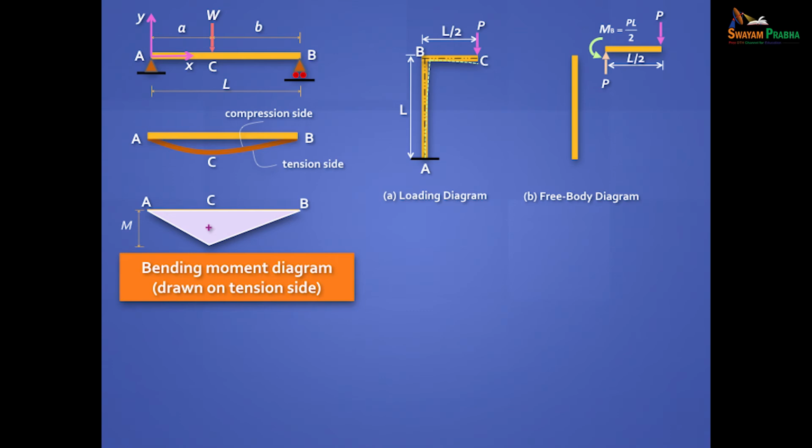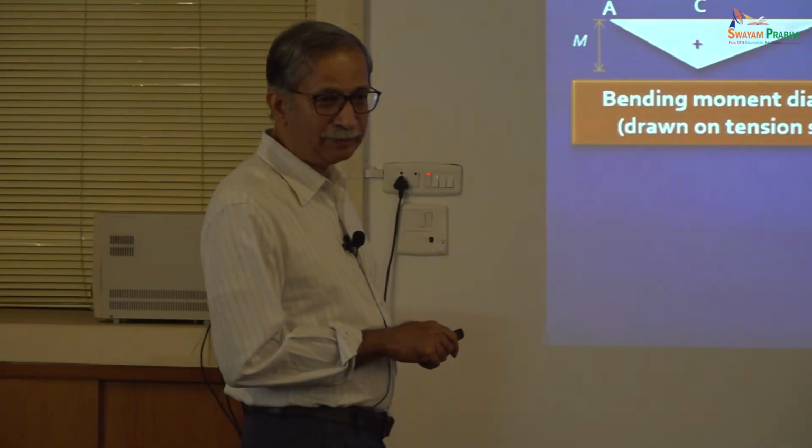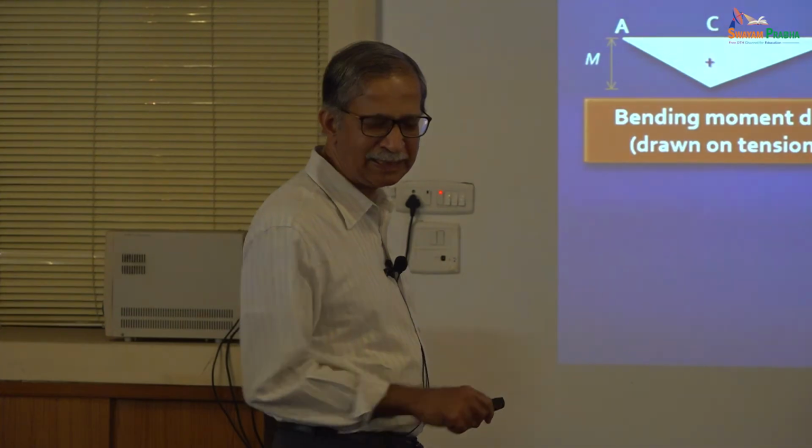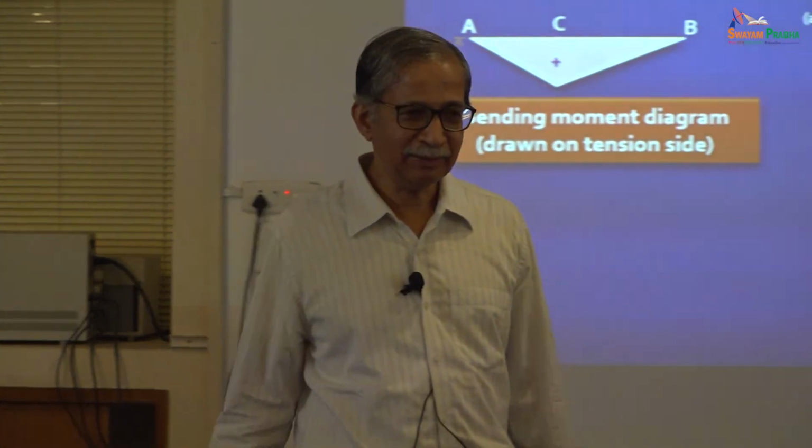Now, bring in Newton's third law. This B is common to this part and this part, and so by shear contact, whatever you put here, you have to put here equal and opposite. Simple, Newton's third law. So P down and moment clockwise. Are you seeing? And then here you will get the reaction straight away. Here equilibrium has to be satisfied, so this P down must be matched with the P up and this clockwise moment with an anti-clockwise moment, right? Simple. Very simple. No complication.